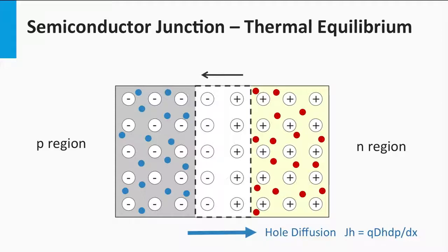It's important to realize that you can vary the diffusion current density in two different ways. As the diffusion scales with the gradient dp/dx or dn/dx, you have either to increase the density of the majority charge carriers, in this case dp, or you have to change the width of the depletion zone, dx. In the following final block of this week, I will show that you can manipulate the width by putting a voltage bias over the solar cell.